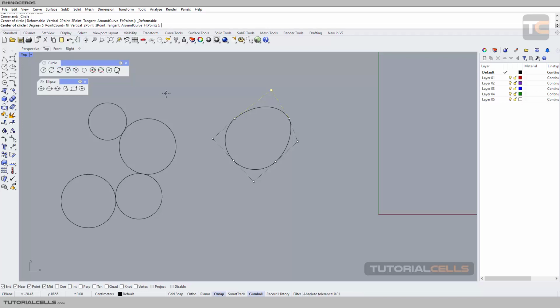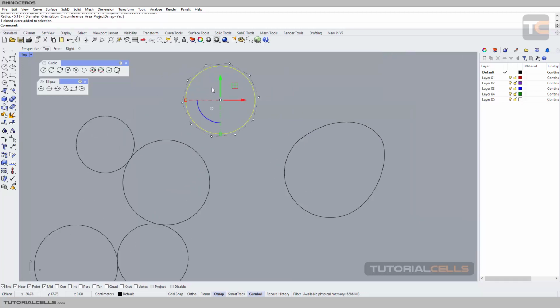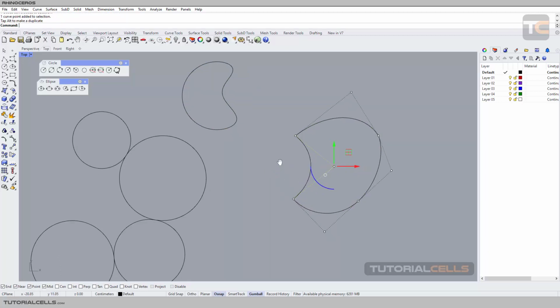That's exactly that icon. I want to select a circle with the center and the radius, and if you select and want to edit that, as you can see, we have 10 points and you can deform it very smoothly. But the regular circle will be broken in these quads. This is the difference between degree 2 and degree 5.